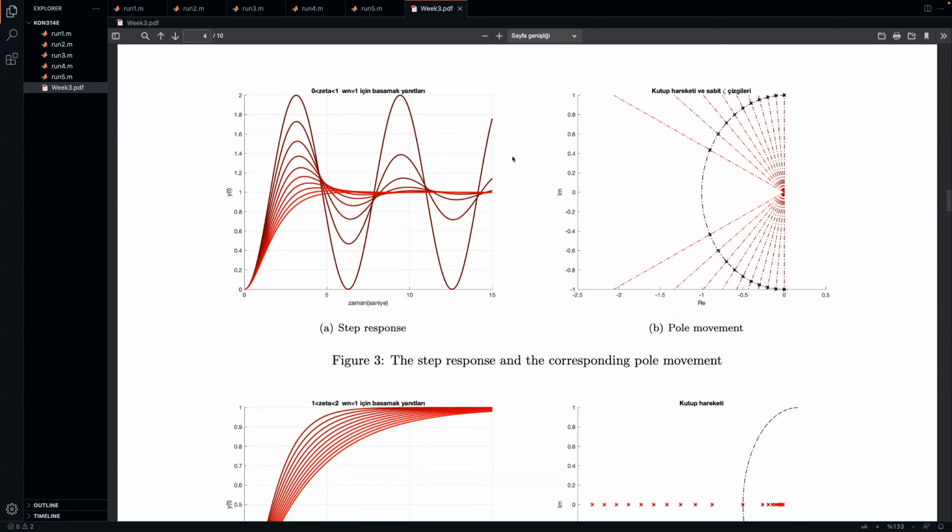And we gave the example where we have this pendulum, and the friction in this pendulum system corresponds to the damping ratio zeta, and you see all the possible different outcomes of a system step response if zeta is between 0 and 1. If it's 0, it's on the marginal stability, and its frequency is calculated directly by omega n. So it's going to be a sine omega n t, because there's no damping, so it's going to be a sine wave.